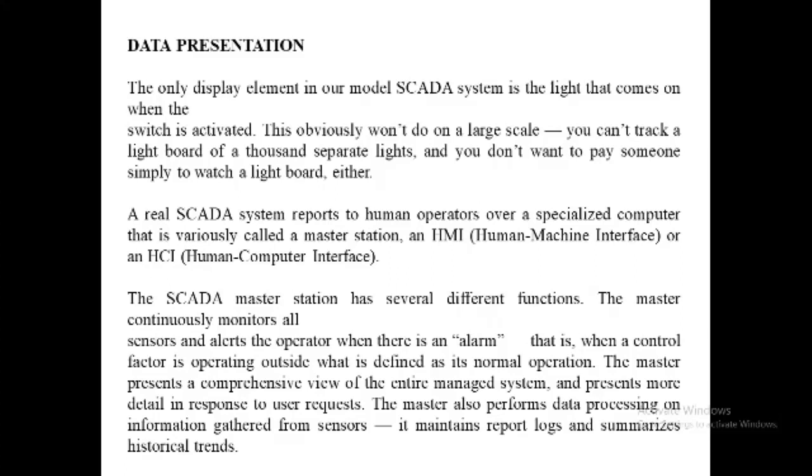Some sensors measure a more complex situation where exact measurement is important. These are the analog sensors, which can detect a continuous change in the analog voltage or current input. The analog sensors are used to track the fluid level in a tank, voltage level in batteries, temperature, and other factors that can be measured in a continuous range of input.